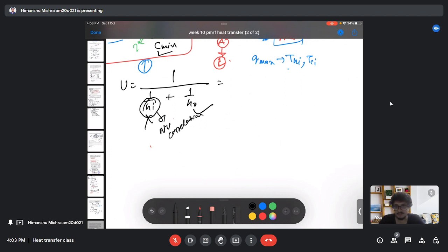To apply the Nusselt number correlation, we need to identify the nature of the flow, whether the flow is in the laminar or turbulent region. For this, we need to calculate the Reynolds number. Since we are given the flow rates, I will write the Reynolds number in terms of flow rate.